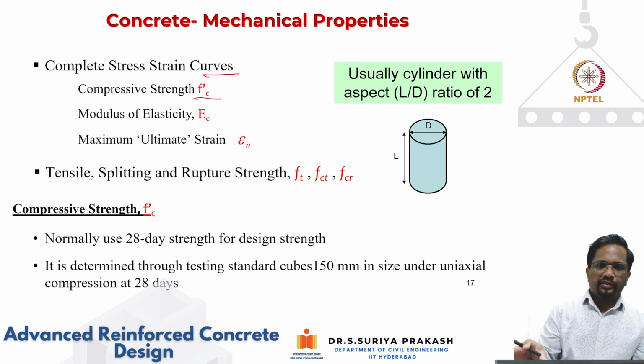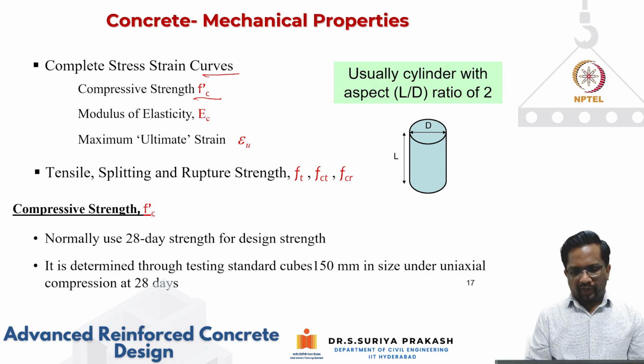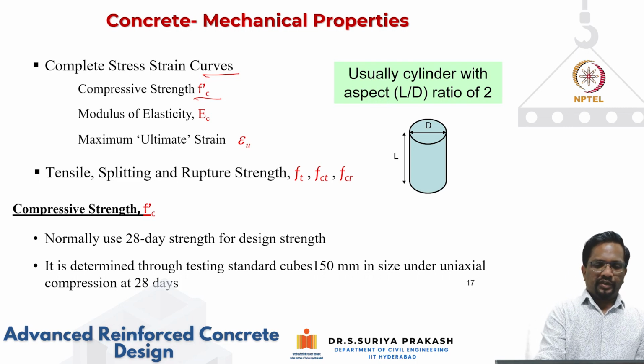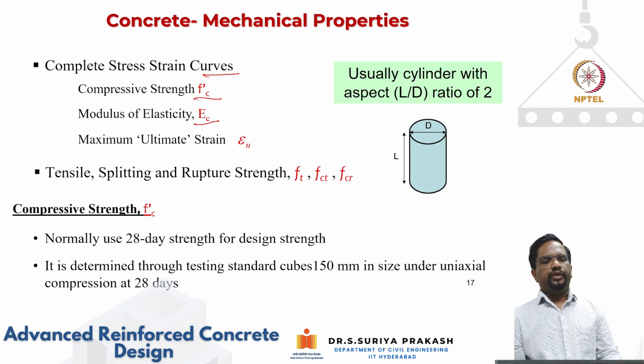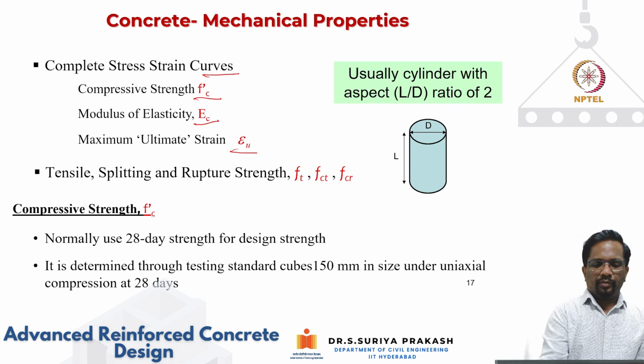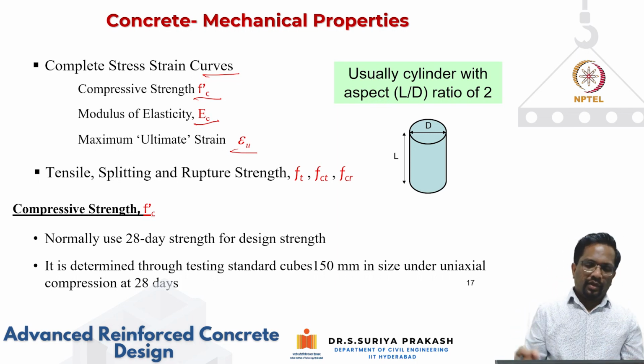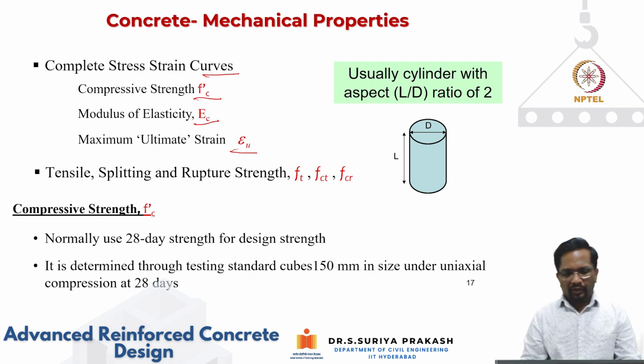If you give the compressive strength of concrete, we have models available that will give you the stress-strain curve, depending upon the range that you work in. So mainly we are interested in f'c, and for deflection calculations and other calculations, we also need the elastic modulus of the concrete. Also, concrete is a brittle material, so we want to know exactly at what strain levels it is going to give way. We need to be careful about that.